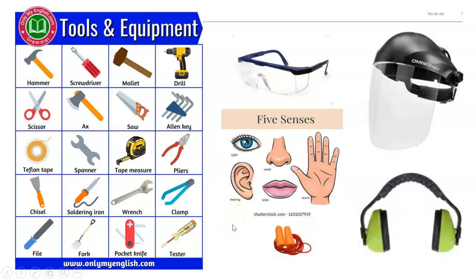And so tutorial number 2 is going to emphasize the safety equipment, the personal protection equipment and clothing, the PPE. We're going to talk about the goggles or protection glasses, the face shields for more dangerous situations. If you're doing something that's noisy, you can use earplugs, or if it's really noisy, it might be necessary to have more significant protection for your ears.